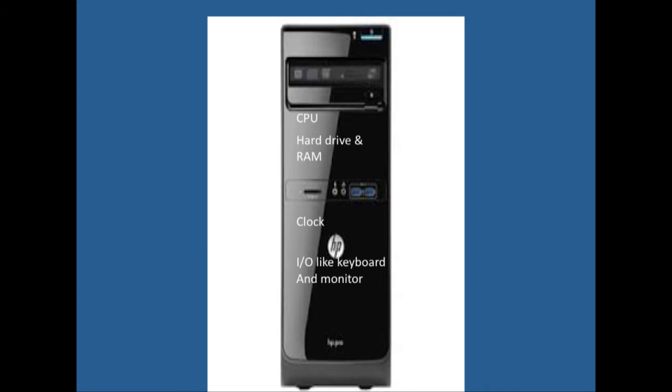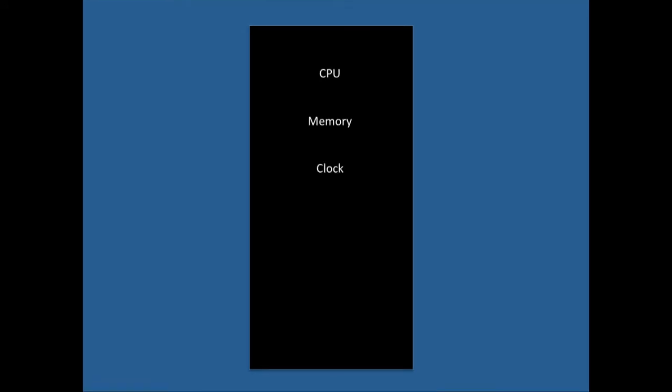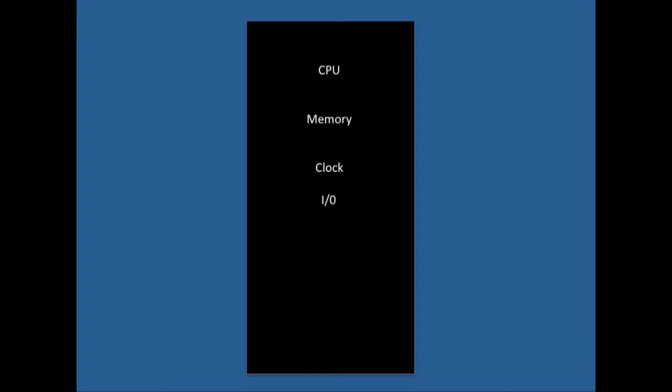Inside this chip is the processing unit to do the logical and mathematical operations. It also has memory so that it can store the program it is running, and it has a clock that is derived from an oscillator. The microcontroller also has some type of input and output. So if you want to do some type of I/O with the microcontroller, you just must hook up the I/O pin to some type of digital logic.